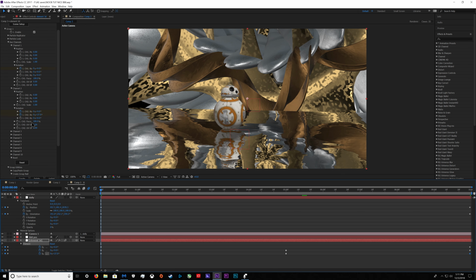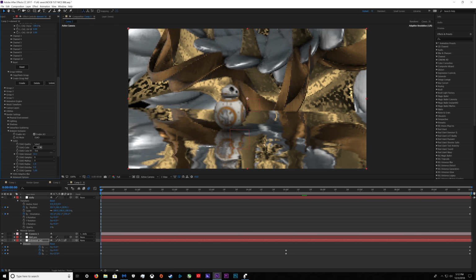Alright, next thing we're going to do is enable ambient occlusion. So go into the render settings, ambient occlusion on, just use SSAO. Ray trace rarely ever works, and this looks good enough. And then just mess around with the radius and the intensity and maybe the gamma until it looks right. And just try to add a little bit of shadow, not much. Alright, we'll go with that.